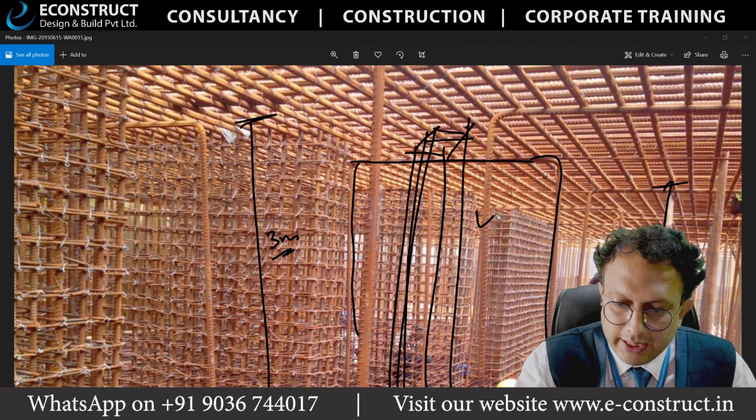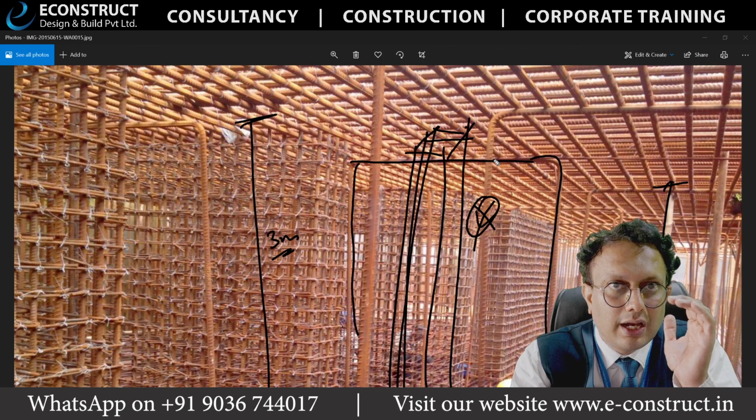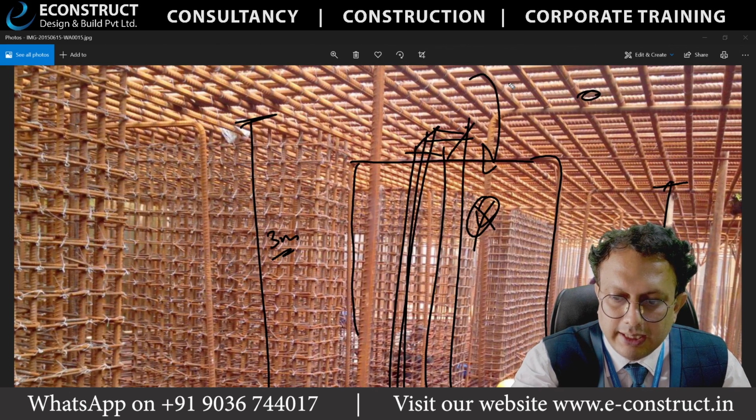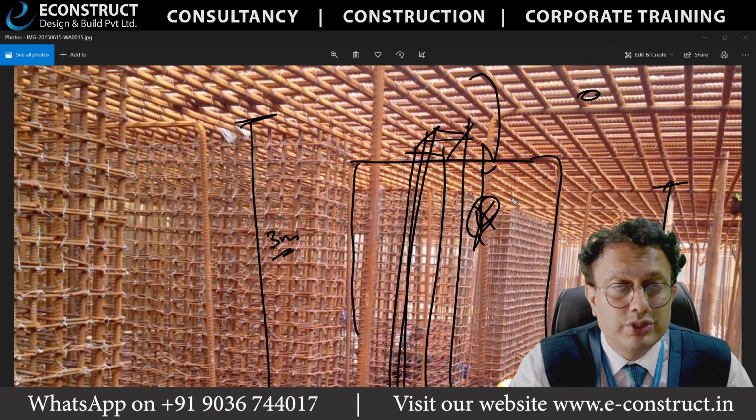Why? Because this tiny little rebar is not enough. This bar will also buckle because of the heavy weight. People will be standing, they will be concreting, and automatically the buckling will happen. It might happen. Very sure. Possibility is very high. Understood?